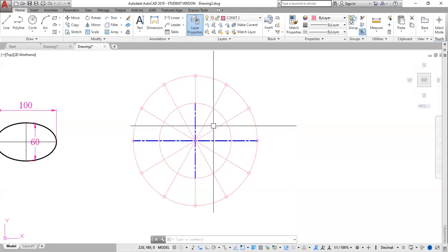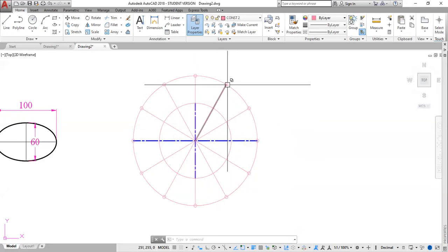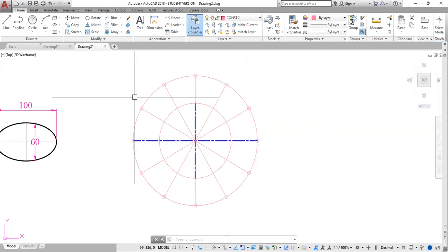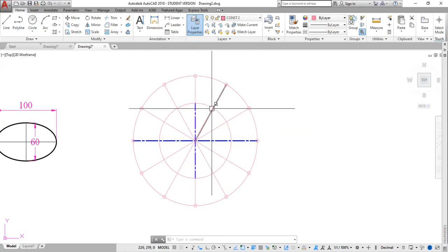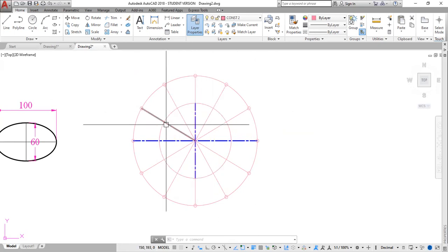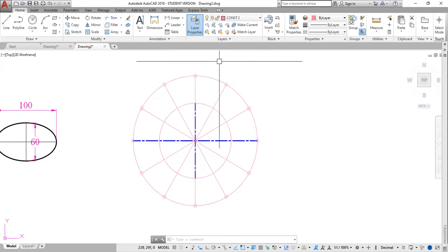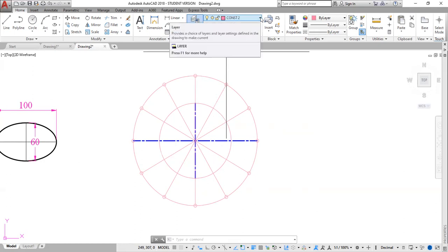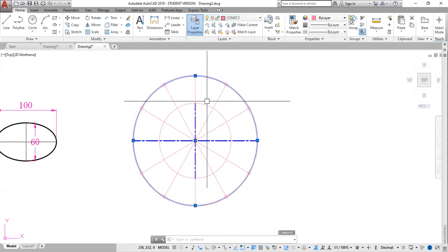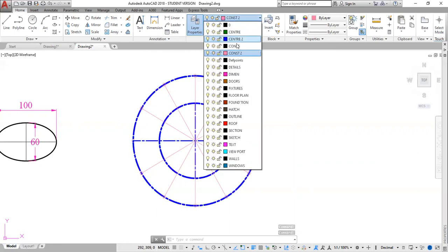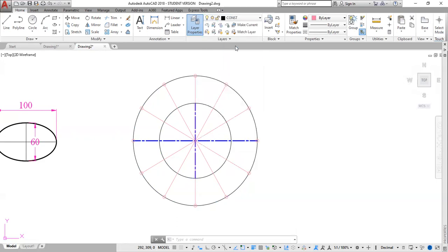Our next step is the rule states that you draw vertical lines down, these, and carry these across. So the points where these points are important. At the points where the radiating lines cut the circle, we're gonna highlight them. Now, I don't like the fact that both lines have the same color. So I'm gonna change one of them. So change this line to construction line. Now I'm gonna draw some lines across these.